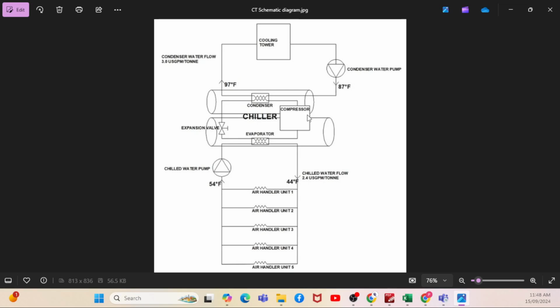Remember, last week we saw that video. There are different types of compressors, for low capacity, medium capacity, and high capacity. If you talk about the water cooled chiller, it is majorly used for high capacity. Most of the time a water cooled chiller will be a centrifugal chiller, because a centrifugal chiller is capable of high capacity. You can talk about a 10,000 kilowatt or 12,000 kilowatt water cooled chiller, very large capacity, with a smaller footprint but covering larger capacity.